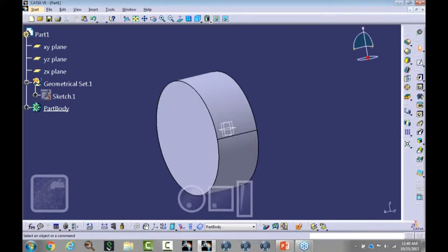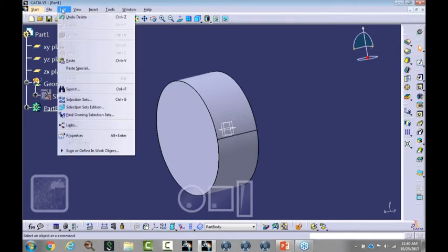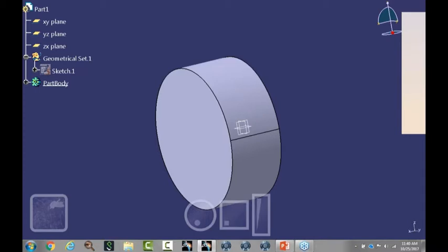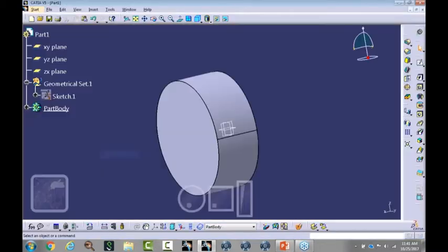By the way, if you are doing some kind of a presentation whereby you would like to not have all of the visual litter here, you can actually go to the View menu, drop down to the bottom, and you can do full screen. So there you have everything that's in the graphic area being presented, but all of the other stuff is not, which are going to be distractions to the vice president, whoever you're presenting to. And then you simply right click in the empty screen area and turn full screen off, and it comes back to your normal settings.